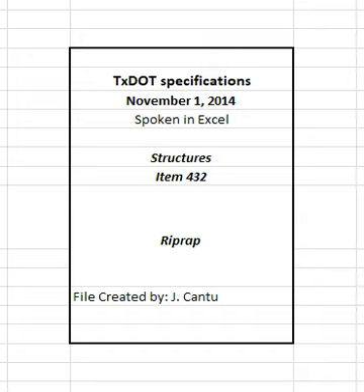3.2.4 Protection. Construct riprap as shown in Figure 5 on the stone riprap standard. Place riprap stone on the slopes within the limits shown on the plans. Place stone for riprap on the filter fabric to produce a reasonably well-graded mass of riprap with the minimum practicable percentage of voids. Construct the riprap to the lines and grades shown on the plans or staked in the field. A tolerance of +6 inches and 0 inches from the slope line and grades shown on the plans is allowed in the finished surface of the riprap.